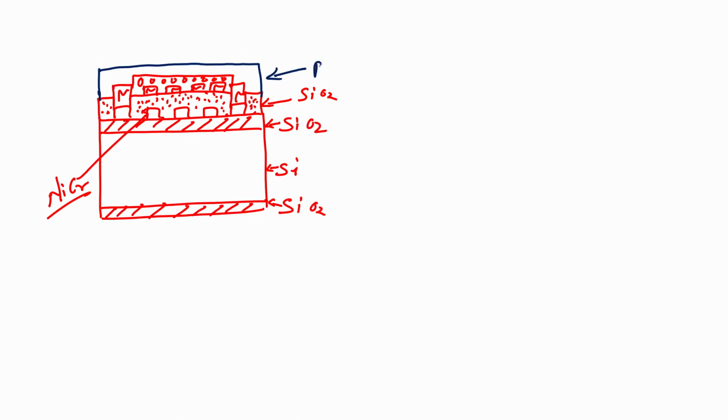This silicon dioxide is deposited using PECVD, because I want to have an insulating layer between the gold pad and the piezoresistive material. What is this material? Piezoresistive material. What is this? Chrome gold. Chrome gold is patterned in which design? What is the design of the chrome gold? Interdigitated electrodes. Okay, easy.